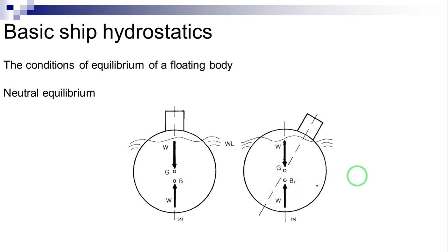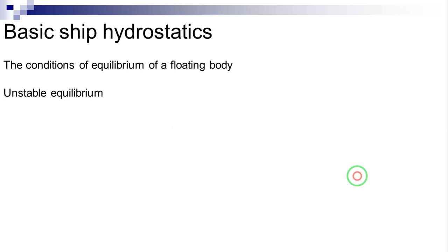The center of buoyancy in a submerged body is fixed, while in a floating body the center of buoyancy generally shifts as the body rotates. Unstable equilibrium. If a floating body displaced from its original angular attitude by an external force continues to move in the same direction after the force is removed, it is said to have been in unstable equilibrium and was initially unstable.